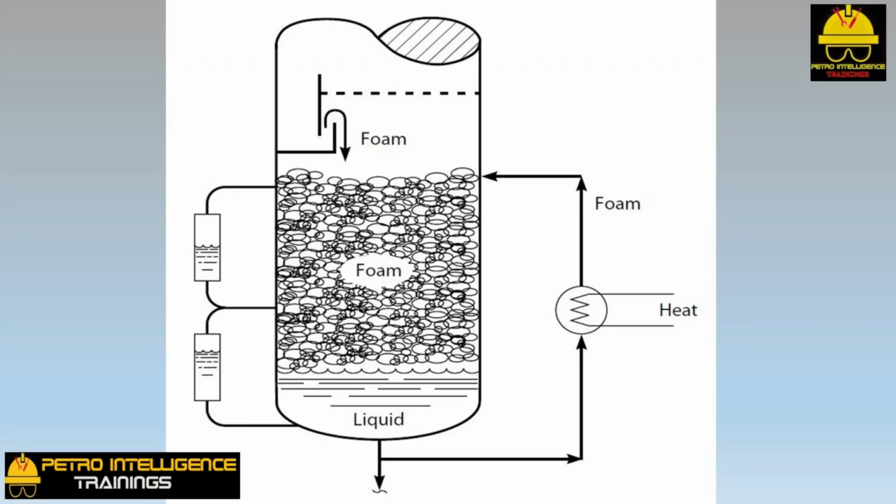This picture shows a distillation tower served by a circulating thermosiphon reboiler. To some unknown extent, some foam will always be found in the bottom of such vessels. Not sometimes, but always. Why? The purpose of a tray is to mix vapor and liquid. This produces aerated liquid or foam. The purpose of a reboiler is to produce vapor.